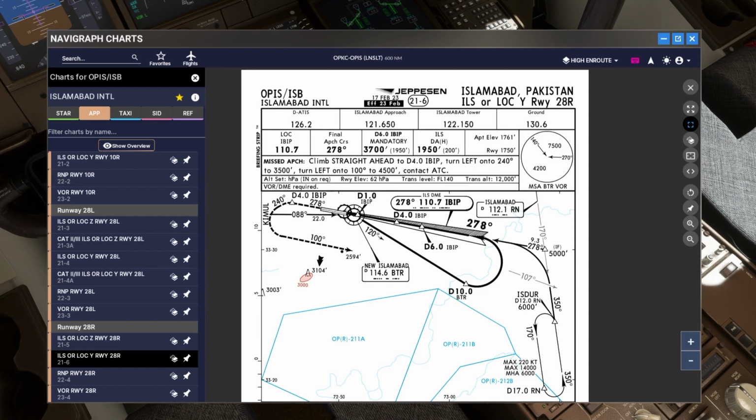But if at a certain height the pilot sees the runway is not properly aligned, or there is some issue, because obviously the human factor has to be there to make the decision whether the ILS has properly aligned the plane with the runway or not. So at this height, the pilot can take a decision to call for a missed approach and then come back again and perform an ILS approach or manually land the plane. So this is the decision height that we have to enter in the plane.